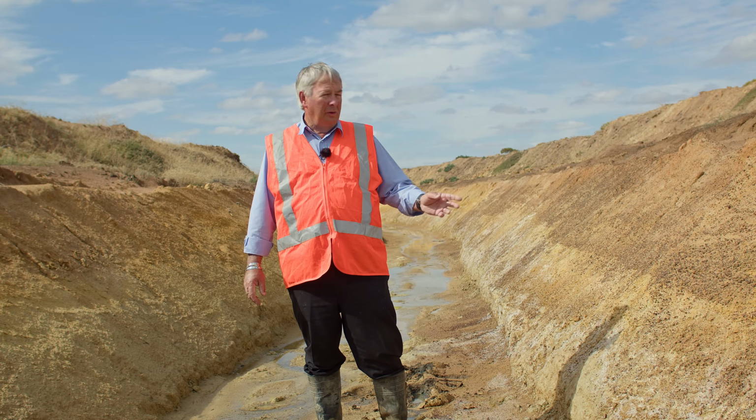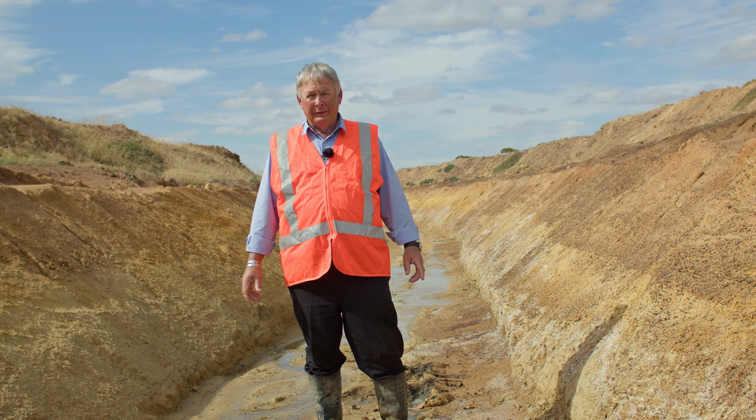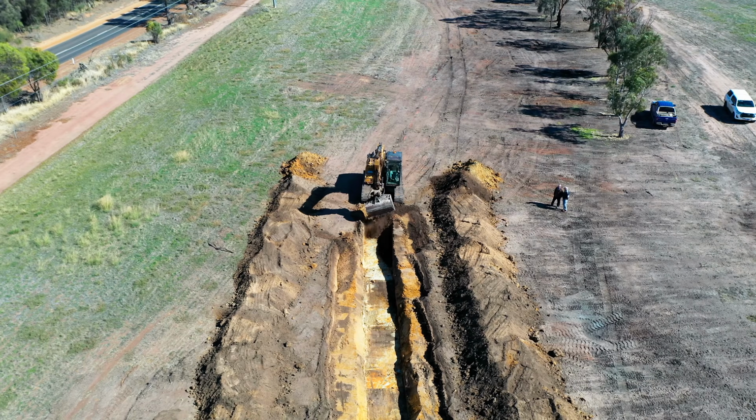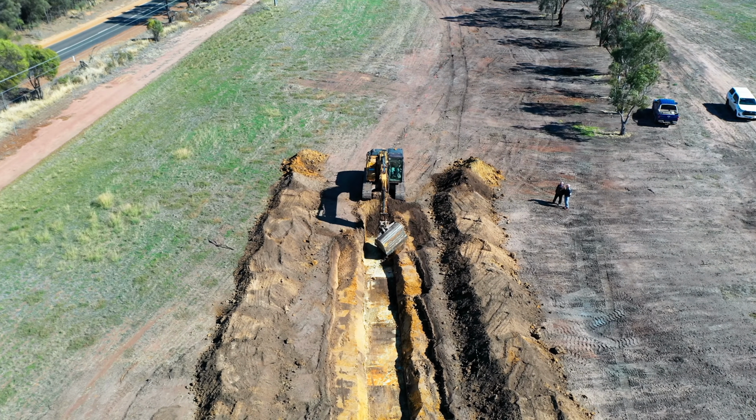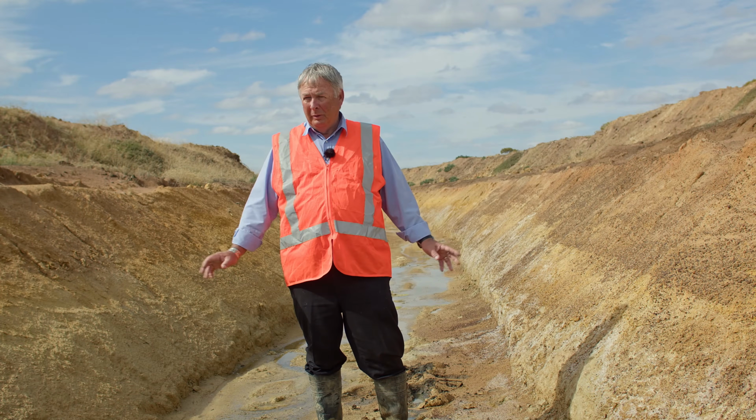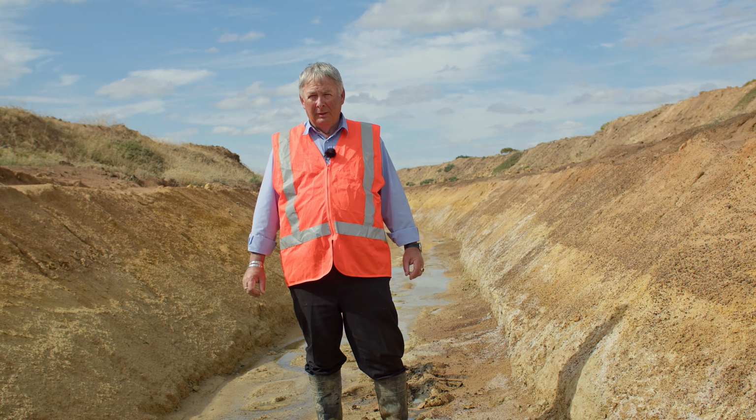At this site you get a good idea of the angle of the batters, and the only way we could get this angle was using a swivel bucket. So we adjusted the angle of the bank because we had a swivel bucket. And here we've actually laid them down a little bit because some of the soil types here aren't very stable.